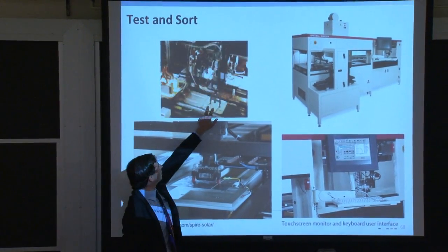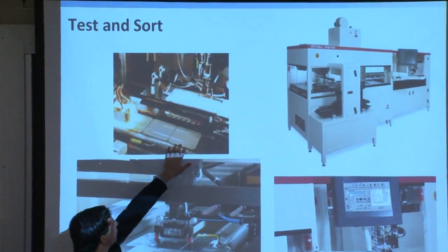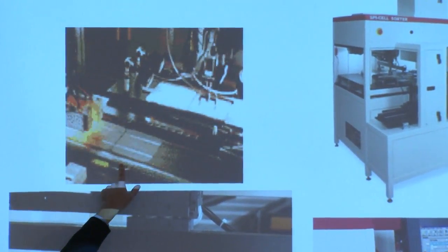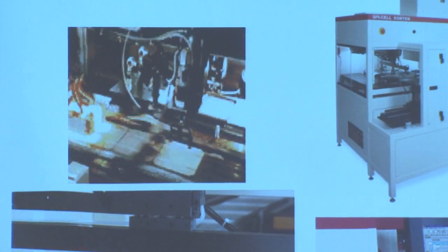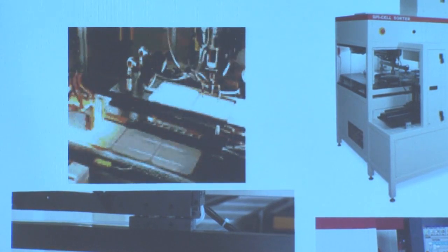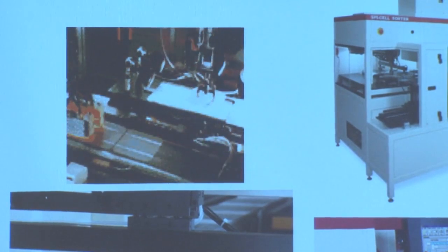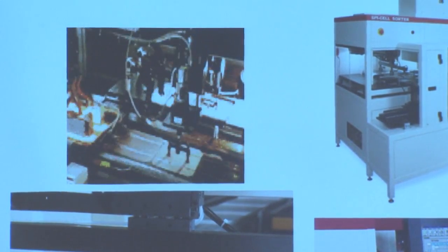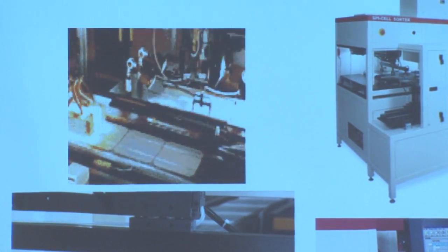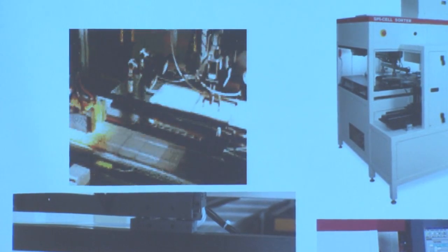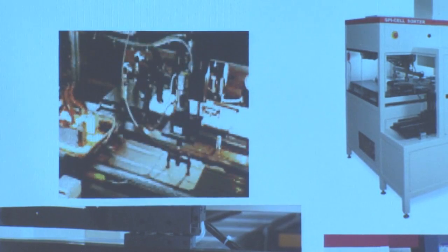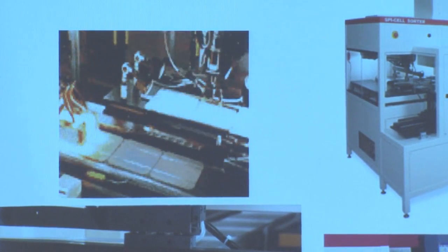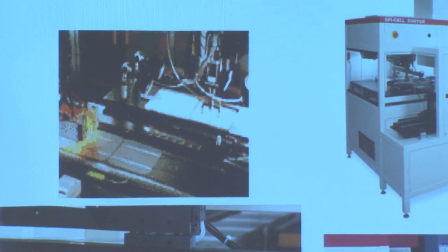So you have wafers being loaded onto a conveyor belt, coming off of one conveyor belt onto another one, and they're moving forward. And what you see right here in very low resolution are 2 probes coming down. This evidently is a 2 bus bar cell, not a 3 bus bar cell like this one. The probes come down and make contact with the bus bars. And the probes have multiple contact points so that the series resistance along the bus bar is not affecting your measurement.